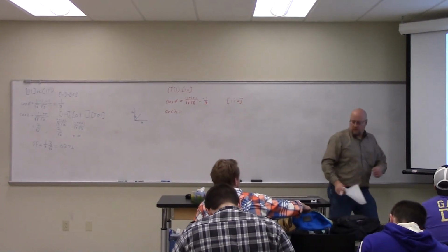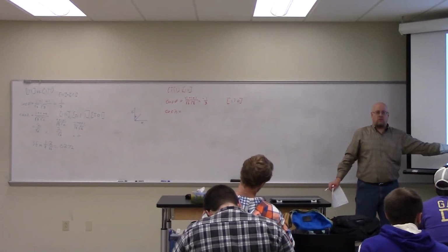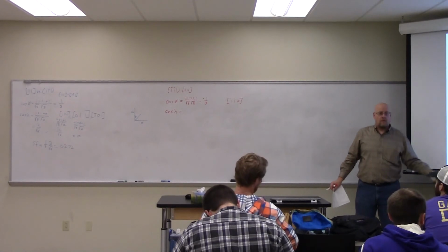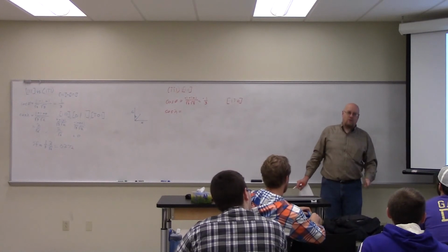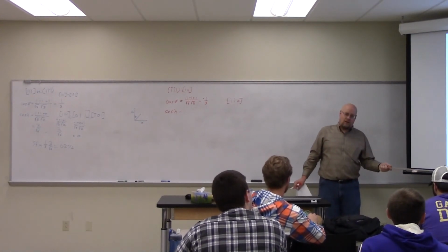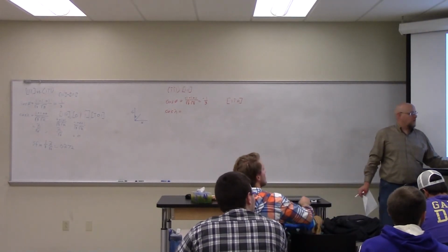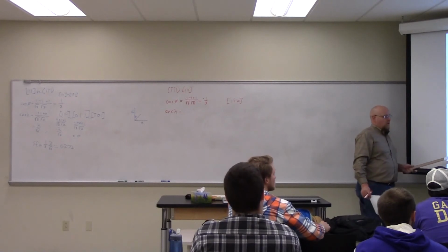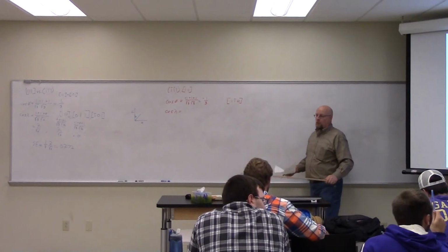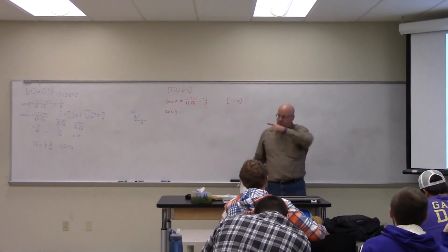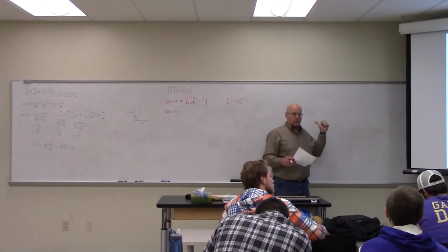So I start in the bottom, in the back left. I go 1 in the A, -1 in the B, and 0 in the Z. That gives me that diagonal. It bugs me how you can pick. Why are we starting with that? Because when you're picking directions, you pick a little point on the line. When you're picking a plane, you pick a point off the plane. I could pick the front right corner, and then I would have 1 bar, 1, 0, which is exactly the opposite of 1, 1 bar, 0. So it's just the 2 directions, this way or this way, but it's the same direction, the positive and negative orientation in the same direction. Does that make sense?